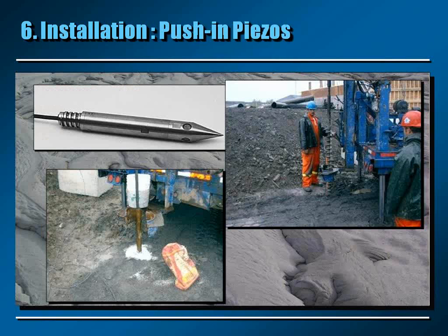Okay. Now, the first type of installation, as you can see on this slide, is the push-in piezometer. You can see on this slide simply that a pilot hole was done, and then the piezometer was connected to rods, and then using the drill rig, we simply push the piezometer to the appropriate level.